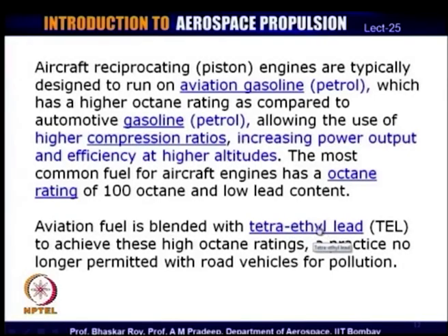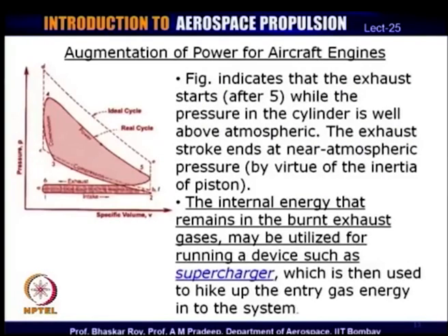And now, we know that in land based automobiles, this addition of tetraethyl lead is now banned because of environmental issues, but in aircraft engines it is still being practiced because aircraft mostly fly at very high altitudes, as a result of which we require the high octane rating that is necessary to operate at very high compression ratios at high speeds for producing high power at reasonably good efficiencies. We now see that quite often an aircraft engine has to operate at high altitudes, where it has to produce good power at good efficiency, and for power production at high altitudes we have a few issues.